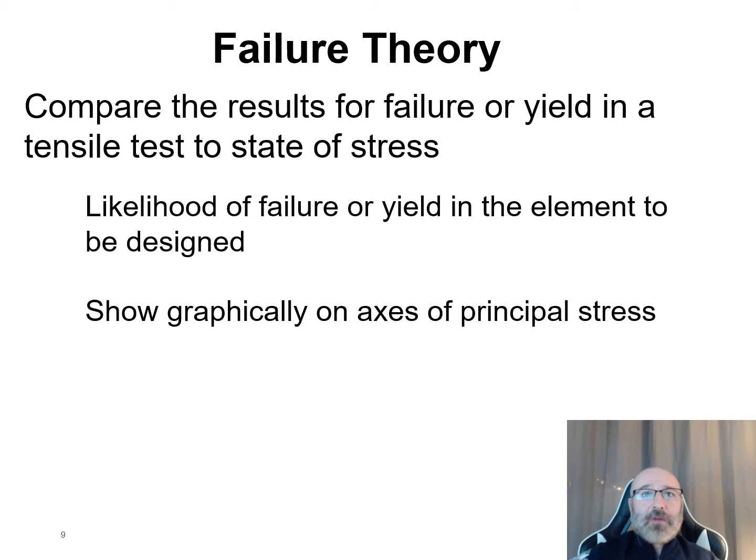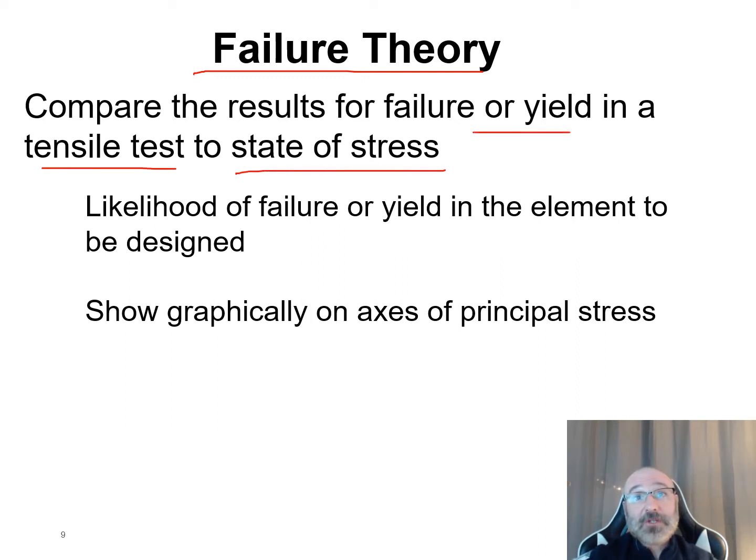So continuing on with our failure theory here, if we want to predict failure, if it's going to occur, one thing that we can do is compare the results for failure or yield in a tensile test to the state of stress right there. So that's why it's important to take these tensile tests and compare that to the state of stress. From that, we can determine the likelihood of failure or the yield in the element to be designed. So this is something we could do in developing it, and in our prototyping as we're making these samples, test and compare from the tensile test and go ahead with our design process from there to tweak it to meet the correct specifications.